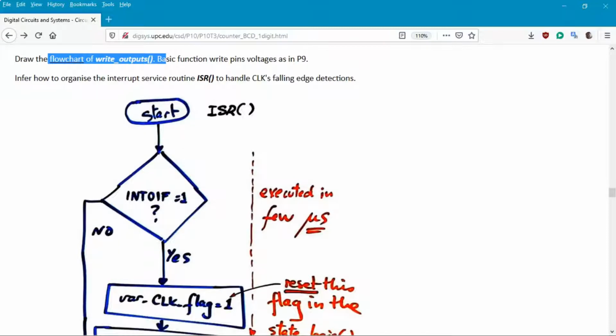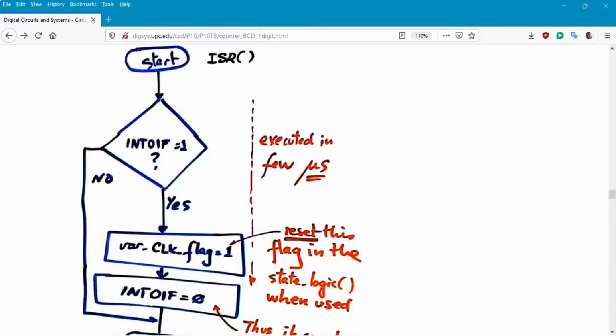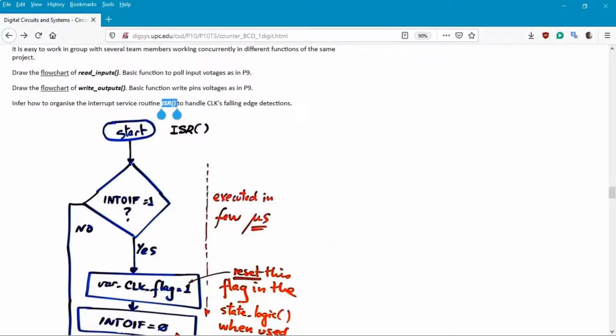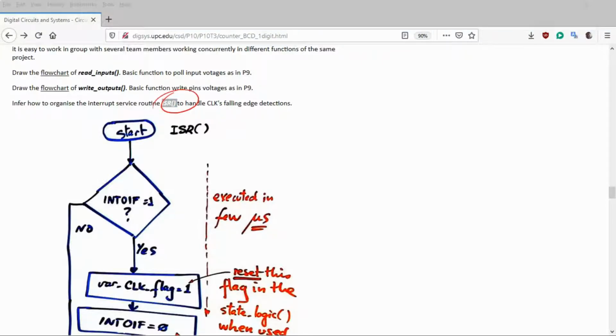Okay, and for example, the interrupt service routine is going to look like this. You see, very simple, because it has to take not a lot of time, some microseconds, a very few number of instructions. So if by any chance you see there has been an interrupt, so very well, what you have to do is to ask, is the interrupt due to the flag of the external interrupt, because remember that is the only possible situation that you are supposing now here.